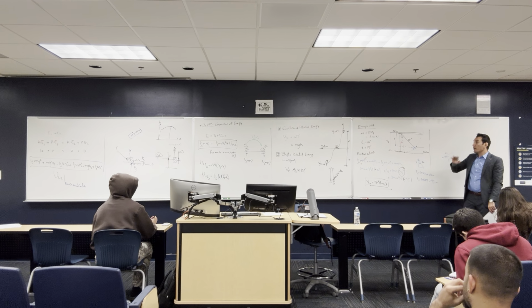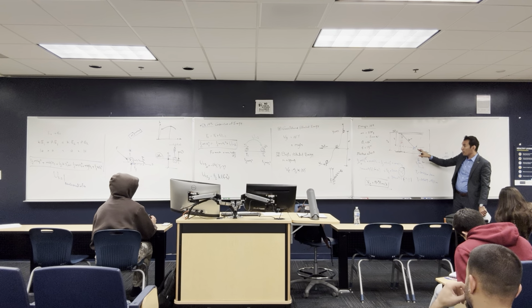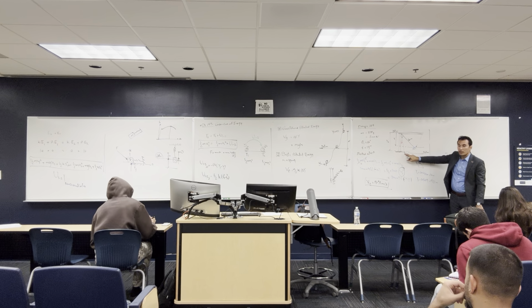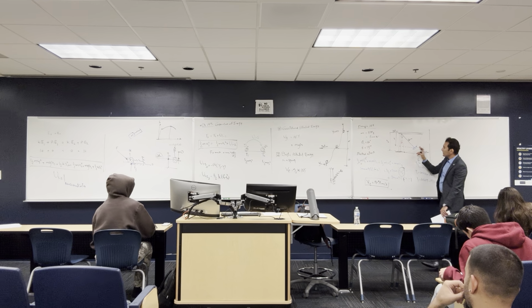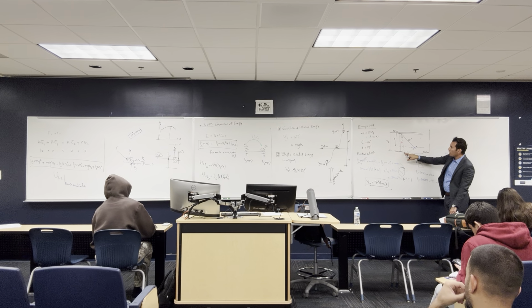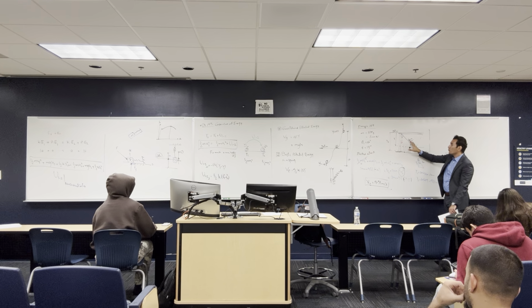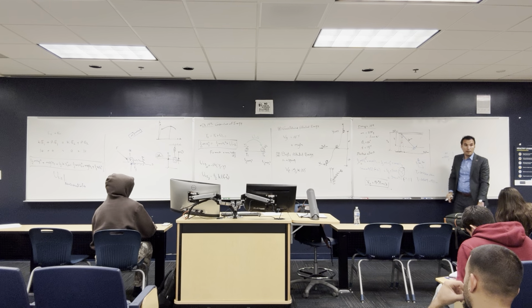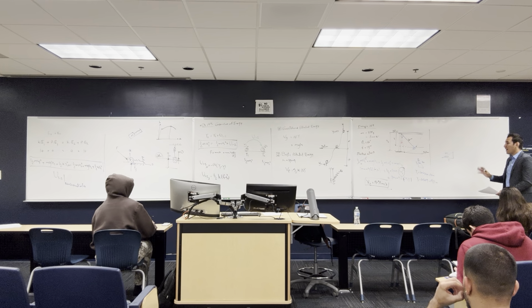They both are going to give you the same answer, but make sure if you put the datum here, yes, this one is going to be 0, but this one is still negative. Because it's the second position, you are going to get the 20 cosine 15, and then you are going to get the 20 cosine 60, subtract them, and the difference is going to be a negative value. All right, so with this, I got the V2.